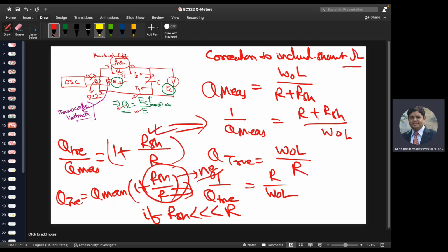Now, once we have done that, we go further. Now you see in this circuit here, you can see that we have RL and since this is a lossy coil, it will have some internal resistance as well as its own inductance, and there will appear some distributed capacitance, right? So that is CD, the distributed capacitance.